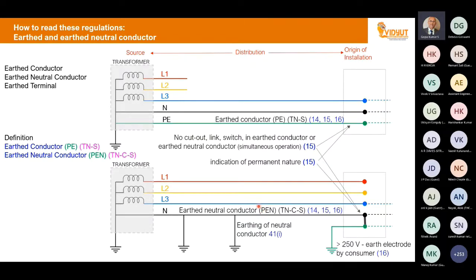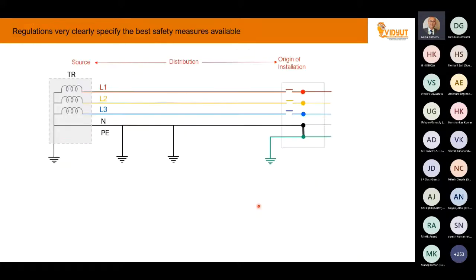It means there is a metallic fault return path in the distribution. In case of any fault at the distribution or at the consumer premise, sufficient fault current returns to the source through the metallic fault return path. As a result, easy identification of the fault is possible and disconnection is quite easy. That was the idea behind these regulations, and that is what is written in the standard.